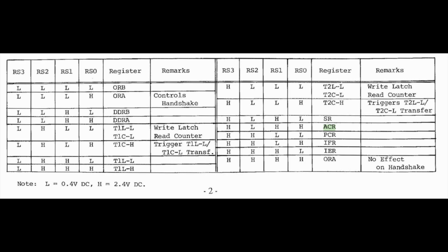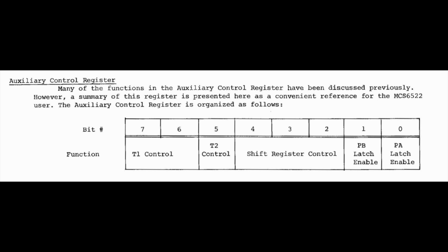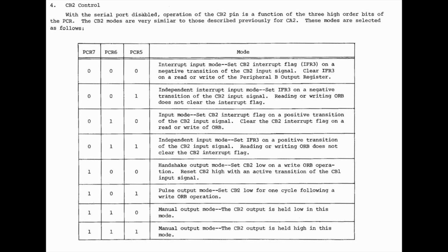Even more fun was low-level coding in assembly language. If one wants to go that path, they are responsible for coding the communication with the 6522 VIA chip. That is, for setting the correct value to the auxiliary control register in order to enable shift-out operation, setting the free-running shift-out mode controlled by timer 2, setting the actual timer value, and finally sending a pattern to the shift register. I started out by copying Lisa's built-in ROM implementation of tone procedures.